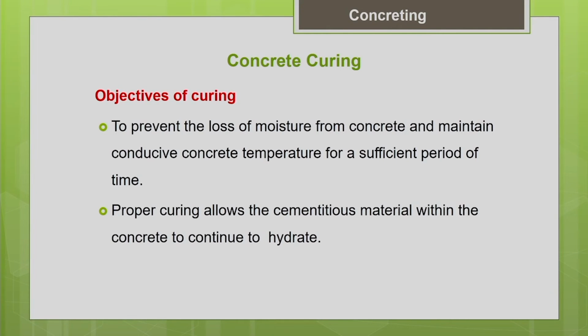After the finishing is done, after the concrete has attained the final setting, the traditional way is we supply water to concrete and facilitate the continued hydration process. The main objective behind supply of water is to prevent the loss of water from within the concrete to the outside environment, as well as to supplement the lost water.